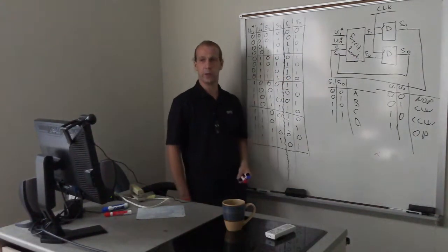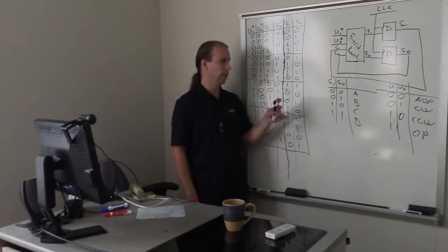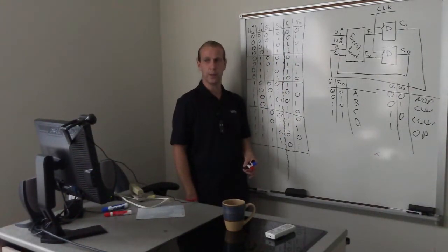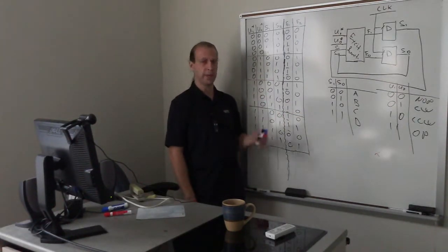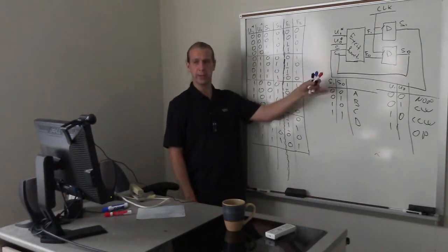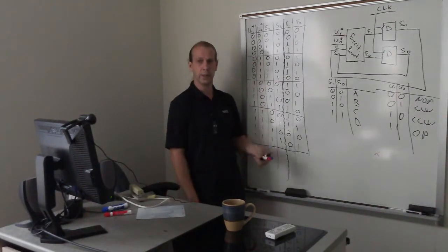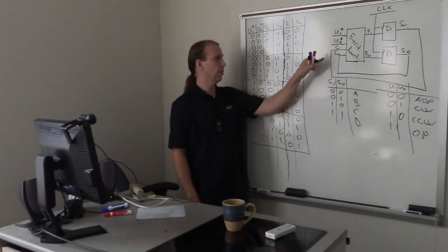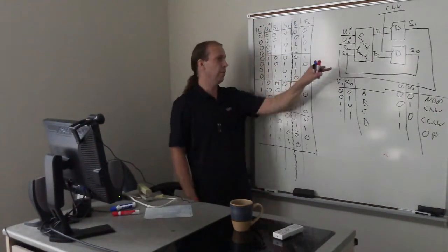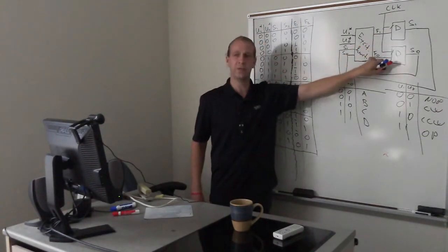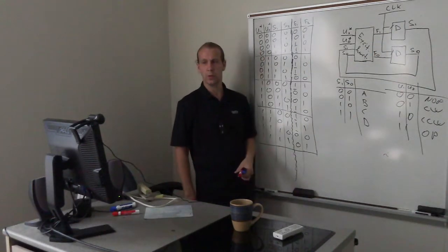And then the magic will start. We press a certain push button. Doesn't matter how we press it, we eventually release it. But at the very beginning of that press, U1 and U0 will be made into a short pulse. Whatever state it was here will be considered with respect to that table, and the new F1 and F0 will make a change in triggers D1 and D2.